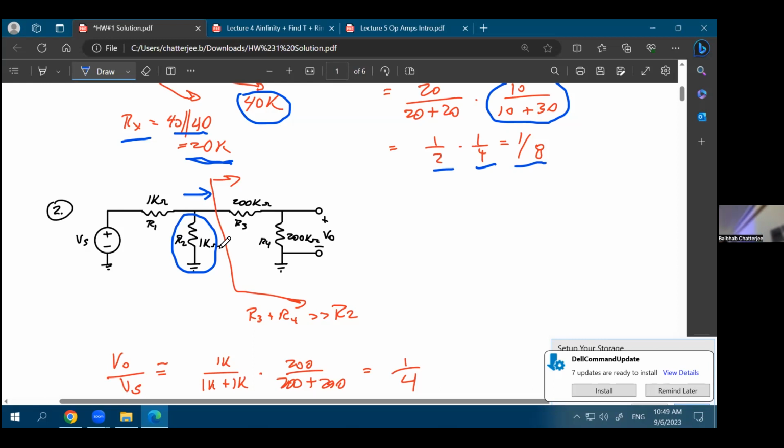If you want to do an exact calculation, it would be 1 multiplied by 400 divided by 1 plus 400. So that is 400 divided by 401, which is almost equal to 1. So in cases like this, you don't even need to calculate that 0.99 something, that exact value, because for all practical purposes, this is equal to 1. So you can approximate this resistance to be 1K.